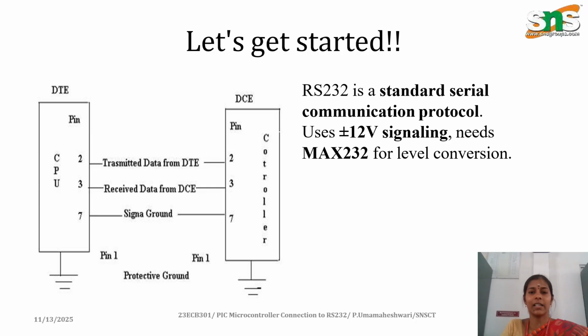Here we'll see RS-232. What is RS-232 first of all? RS-232 is a standard serial communication protocol which is used with up to plus or minus 12 volt signaling. It also needs a MAX 232 for level conversion.